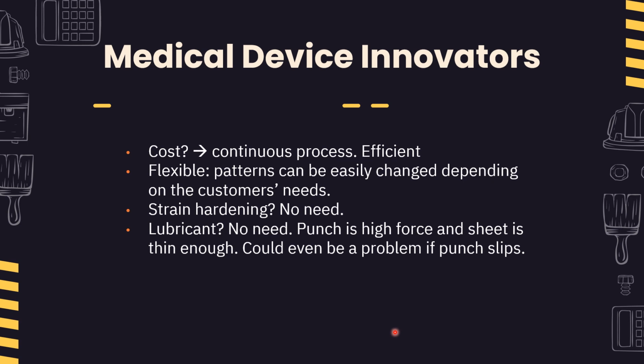Finally, the use of lubricant is not needed, and I don't think it's even recommended. The punch force is sufficiently high to cut the thin sheet of titanium, and the use of lubricant could let the punch slip and produce undesirable holes.